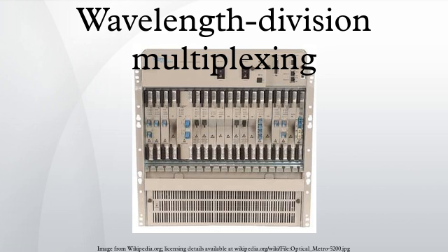DWDM systems. At this stage, a basic DWDM system contains several main components: a DWDM terminal multiplexer. The terminal multiplexer contains a wavelength converting transponder for each data signal, an optical multiplexer and where necessary an optical amplifier. Each wavelength converting transponder receives an optical data signal from the client layer, such as synchronous optical networking, SONET/SDH or another type of data signal, converts this signal into the electrical domain and retransmits the signal at a specific wavelength using a 1550 nm band laser.